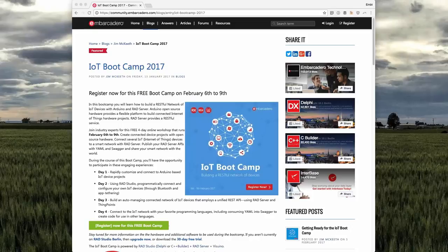The VIN pin, I have to look at the exact voltage range, but it is listed in the Arduino boards, something up to like 9 volts you can put on that pin. And the Arduino Nano has its own voltage regulator on the board, so it will convert it automatically to 5 volts and everything is going to work just fine. So yeah, you can power it with an off-the-shelf battery.